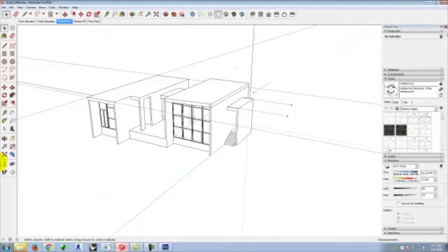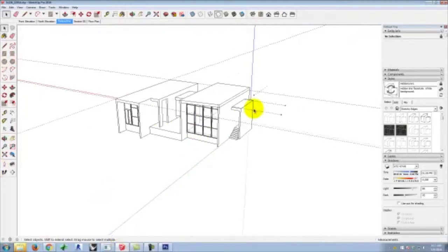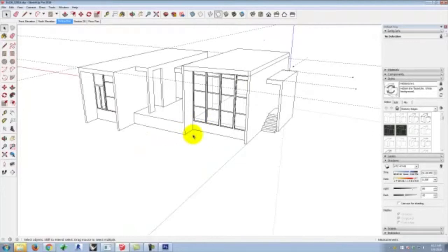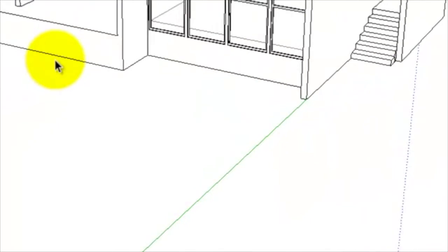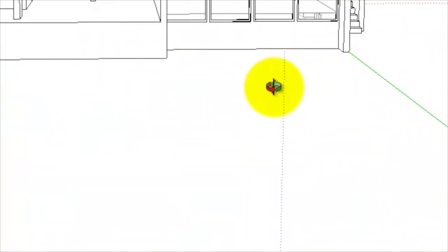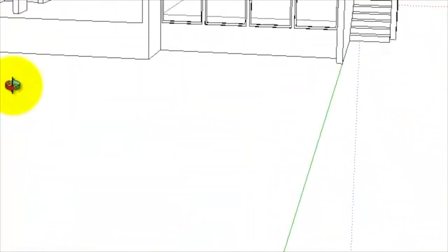So when we go to do a plan of our SketchUp model, we need to establish where this 4-foot line is. It doesn't have to be exactly 4 feet, but somewhere around 4 feet. Generally, 4 feet is the convention. I need some kind of a guide that's going to help me figure out where 4 feet is. It's a little bit complicated because I've built my building such that I have some foundation below it. So I'll start with just a basic square that's in front of my building.